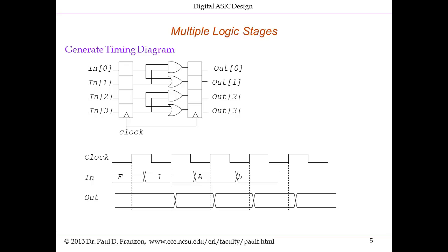Okay, well now you've produced that timing diagram, or you chose not to, and I will present the solution before showing how some of this can be calculated. Of course, before the first rising edge of the clock, we don't know what out is. In fact, even after the first rising edge of the clock, we don't know what out is. It takes 2 clock cycles, and this is important to realize, it takes 2 clock cycles for a change in in to affect the change in out, because there's 2 stages of registers in between.